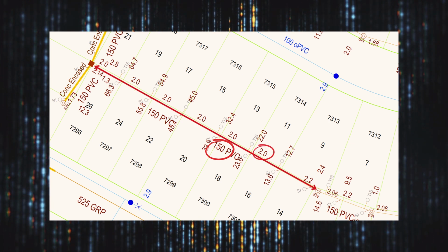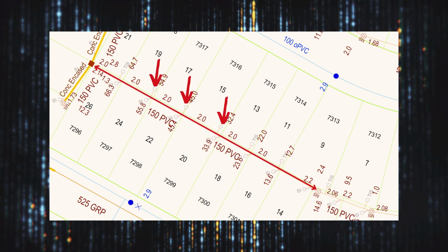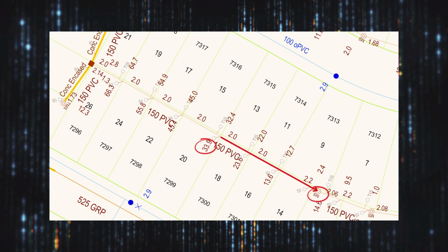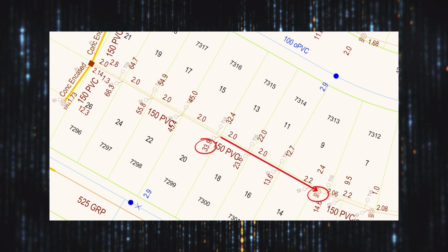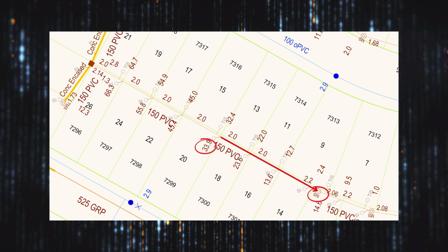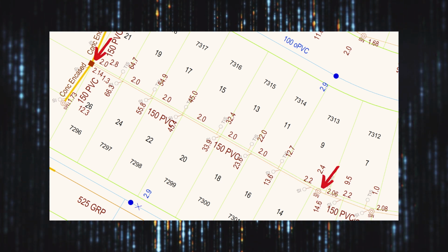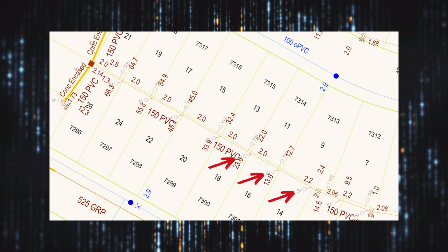The little lines represent the property connection point and indicate the direction of the flow, and the distance here is meters to the nearest maintenance shaft downstream. This dimension is handy when digging in the future to find the connection point. The squares represent maintenance shafts that typically occur at each bend in the network. IS stands for inspection shaft.